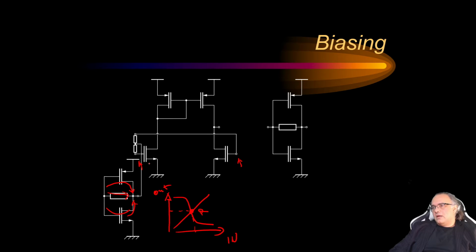So now we know that these transistors, because they will be very much similar to this transistor here, these two transistors, the input differential pair, will be biased at an almost optimal operation point, which is this one, of course.